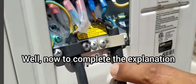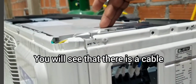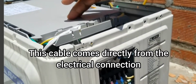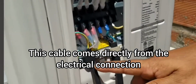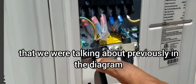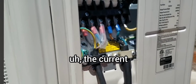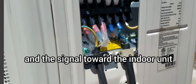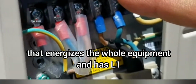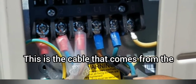Well, now to complete the explanation, we are going to look at the equipment already installed. You will see that there is a cable that energizes the card of the outdoor unit. This cable comes directly from the electrical connection. And then we have the intercommunication cable that we were talking about previously in the diagram. This cable carries the current and the signal toward the indoor unit. And this cable is the one that energizes the whole equipment and has L1, neutral and ground.